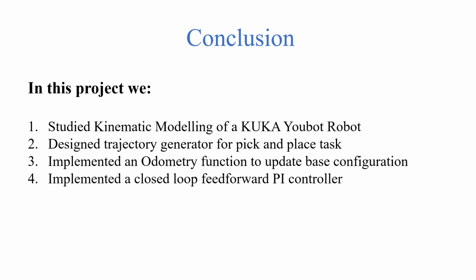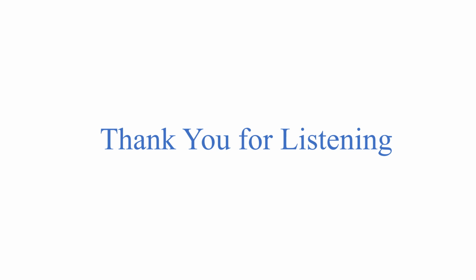Now, this concludes this project in which we studied the kinematic modeling of a KUKA Youbot robot. We designed the trajectory generator for a pick and place task. We also implemented the odometry function to update the base configuration as the robot moved. We also implemented a closed-loop feed-forward PI controller and demonstrated the results in the CoppeliaSim simulator. And that's it. Thank you for listening.